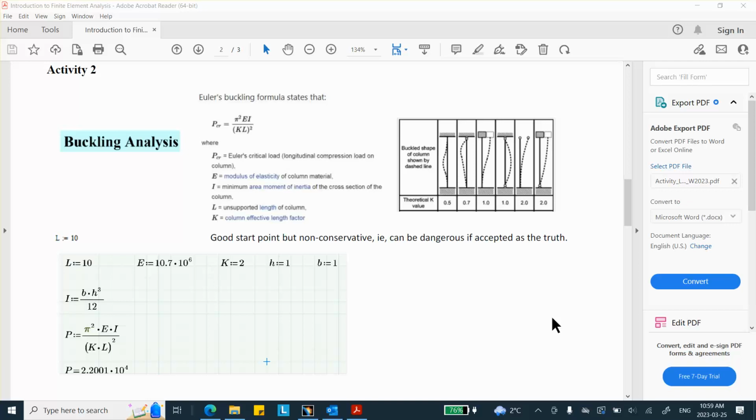The load is perfectly aligned with the axis of the beam and stuff like that, which is impossible to do in real life. Now, Catia does linear buckling analysis, and therefore, what happens after the buckling is predicted cannot be done in Catia. In other words, the post-buckling stage cannot be done with Catia.